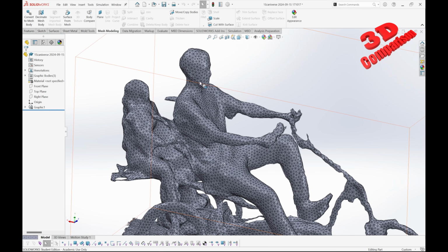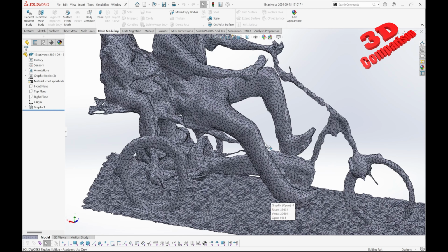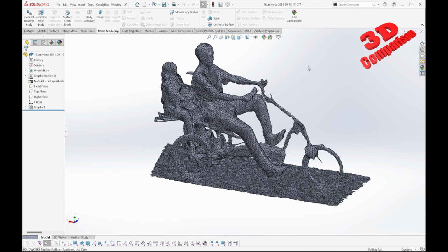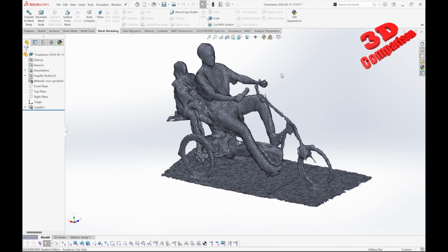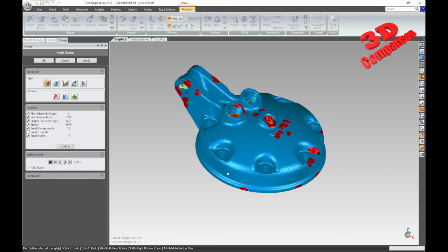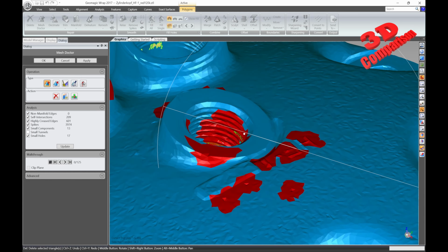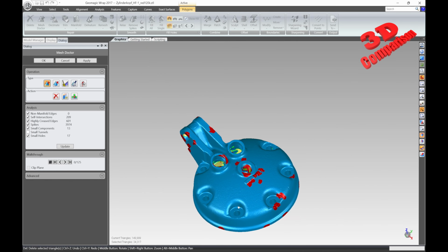But if you have something that you model within SolidWorks, you can save that as a STEP file or as an IGS file, and that should transfer without any problems, because usually the problems are associated with self-intersection, high creases, and also non-manifold edges. This is something that can also be easily cleaned within CATIA.